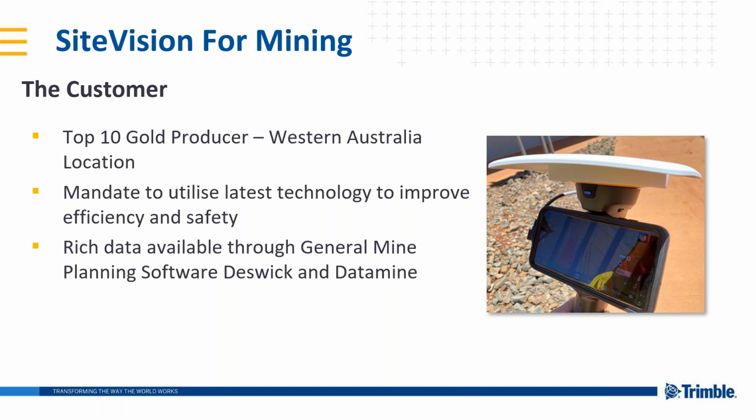So the first problem we had to overcome was taking that data and getting it into SiteVision. The workflow we developed here was to go from DXF, from the mine planning packages, into Trimble Connect and then onto the device. This can be achieved through a few ways. They're looking at setting up teams with Trimble Connect so they can be sent to the survey team or the geology team and so on.